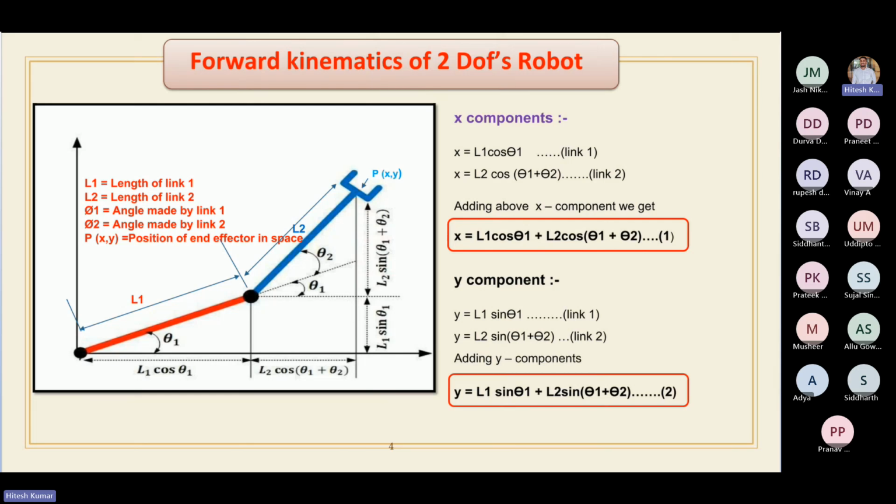Cool. Okay, good. This was only the forward kinematics. We will have all these values in forward kinematics: the relative angles between the links and the lengths of the links. We'll put these values in the equation, calculate the projection on the x-axis, y-axis and z-axis, and calculate the position of the end effector. Yes or no? Everybody agrees? Okay.